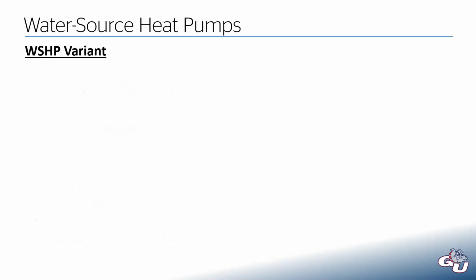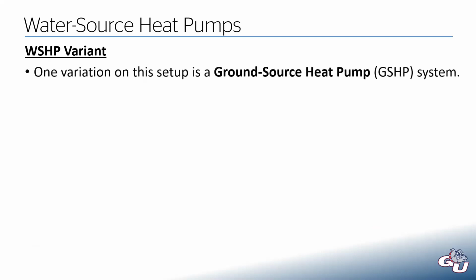So that's the bread and butter of water source heat pumps. They've been around for a long time. This isn't new technology. We don't see them super often because they are a pretty expensive system, but it is kind of a neat idea. And like I said earlier, VRF systems are kind of doing the same thing, just with a refrigerant network instead of a water network. One variation on this is what's called a ground source heat pump system, which is often abbreviated